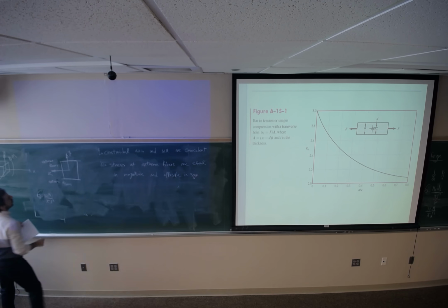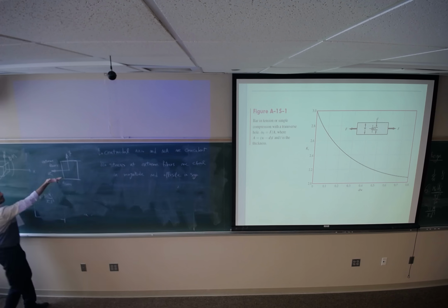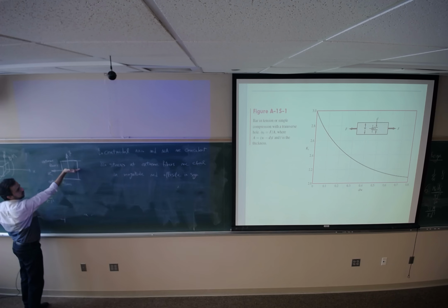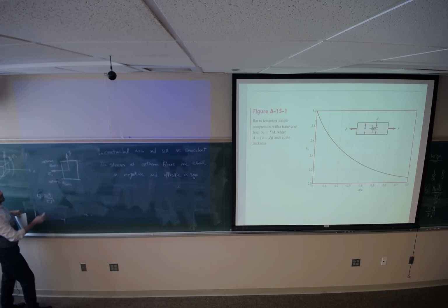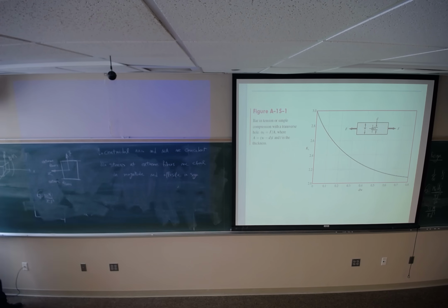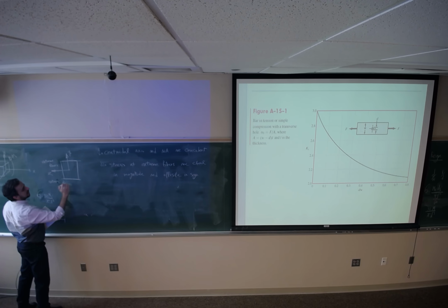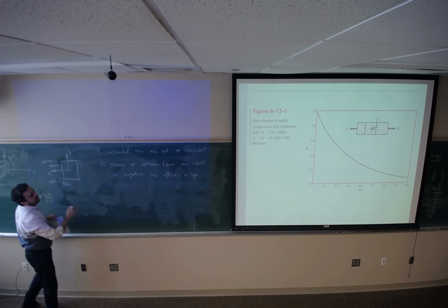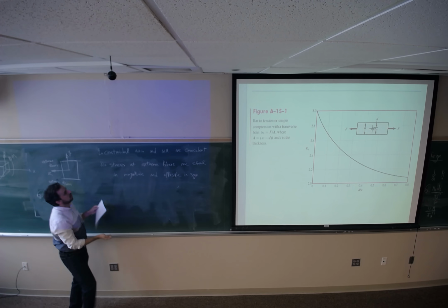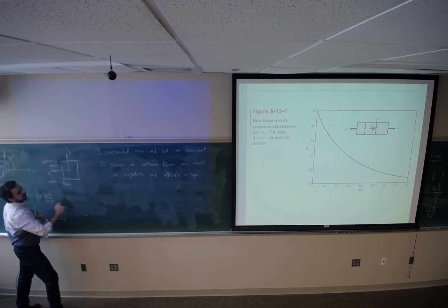So for this case of the loading, any point at the top of this line, the neutral axis, is going to be under compression. So this line is going to get the maximum compressive stress, and this line is going to see the maximum tensile stress, but the magnitude would be the same for both extreme fibers because they have the same distance from the neutral axis.